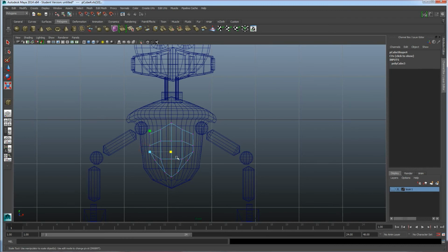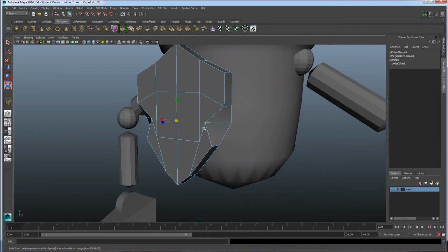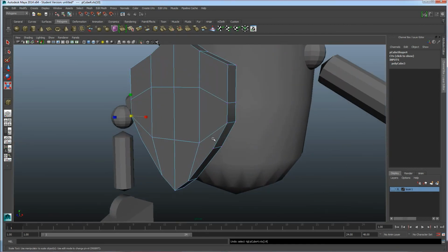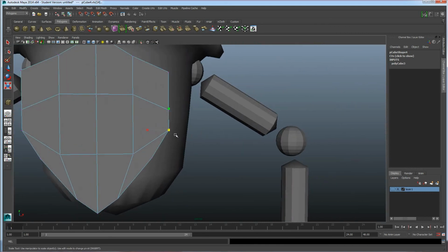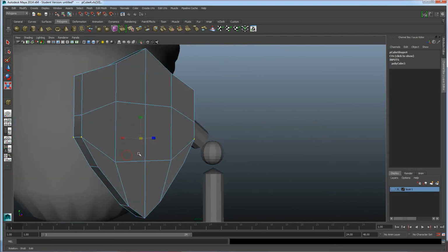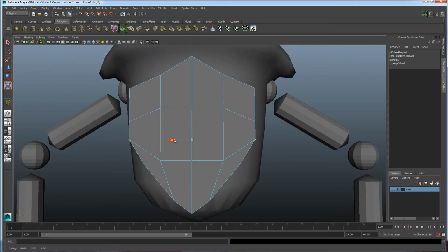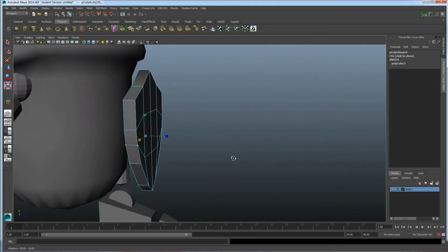And also note, when I'm grabbing these, I'm sliding across by selecting them. If I just click it once and click the other one once, the scale, I'm not grabbing the piece behind. I'm only grabbing the ones in the front. So by selecting through it, by going a border select, it'll grab both pieces, even though you can't see both from the front view. It grabs front and back, so when I scale it this time, it doesn't have that problem. Alright, so that kind of builds a bit of a shield in front.